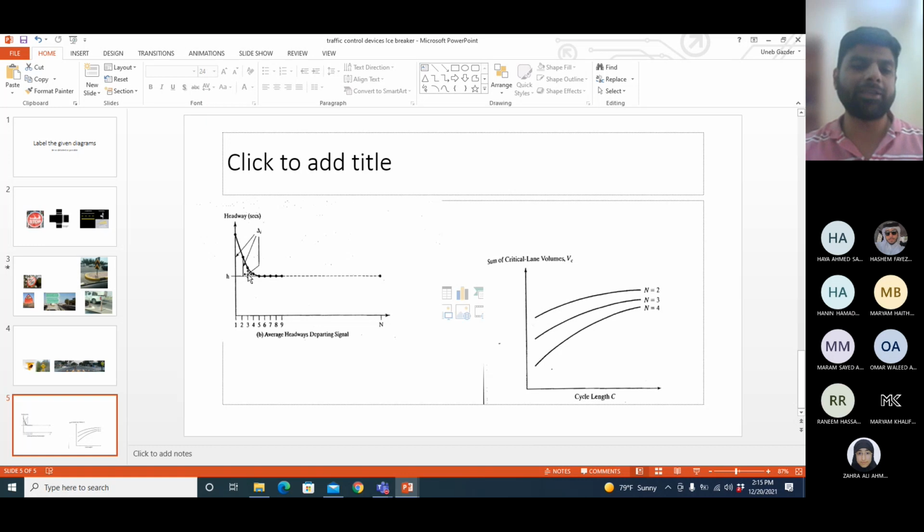So the headways of the first 3-4 vehicles in the queue had extra values of delta in them, so that's why we did not call them saturation headway. Okay, so this is basically showing the trend of decreasing headway from one vehicle to another in the queue.